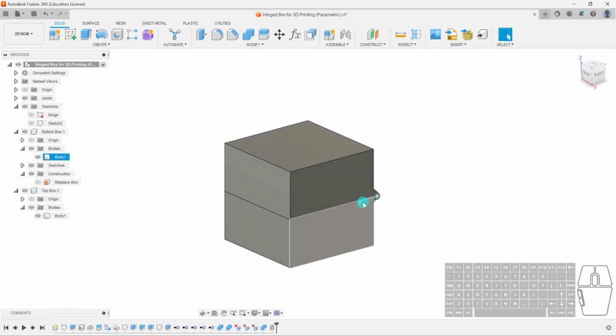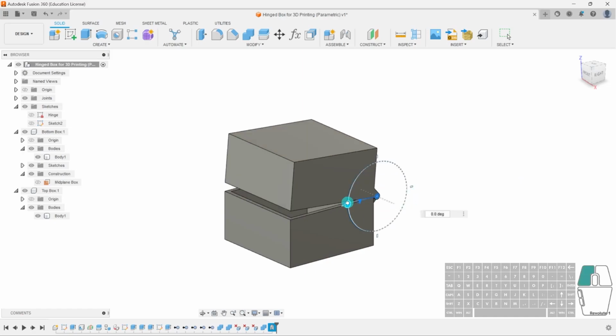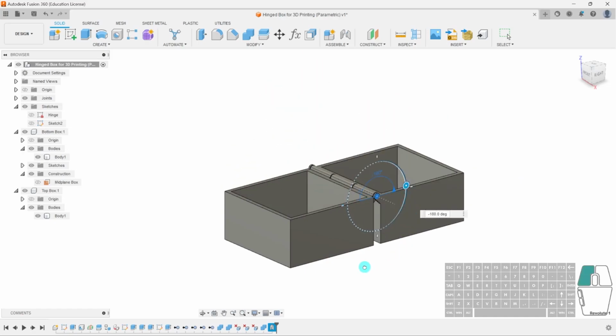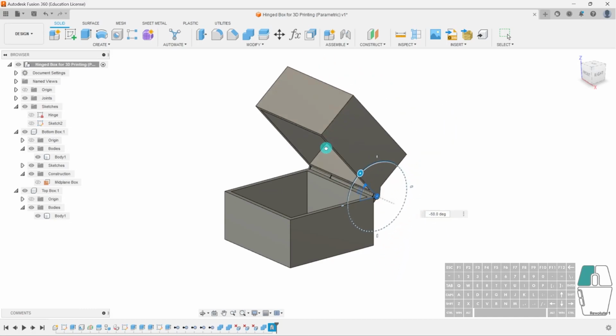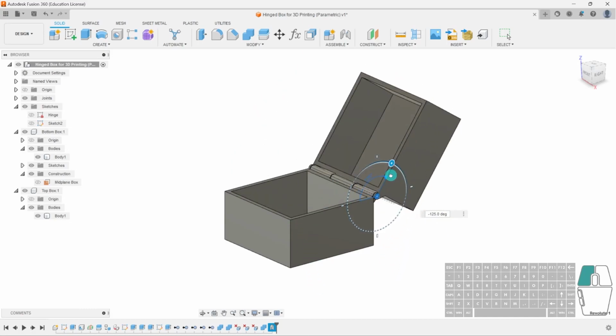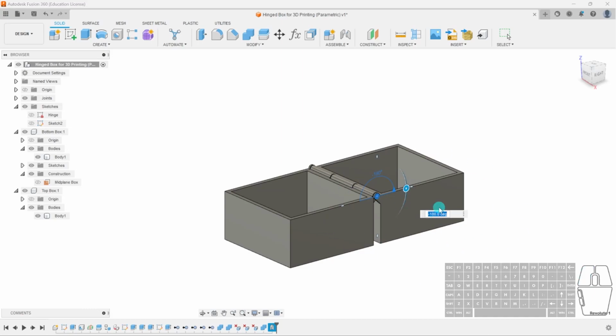And so now I've got a joint. I can always select this little flag here. I'll click on it. Oops, don't know why it didn't. So once I click on it, it'll give me a rotation. I can always just rotate this to 100, and you can see I can't rotate it further down because I have the limits. So now I'll leave it like this.